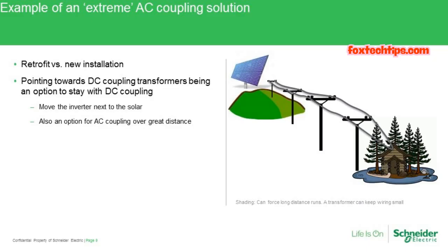That then the AC coupled portion with the XW Plus inverter, batteries, and just power distribution was all done down at the home. So it was really nice to have an outdoor rated grid tie inverter up there, and then we just simply had a power shed down below that took all that power, stepped it down, and was usable inside the home. Really, really nice way to do this configuration.